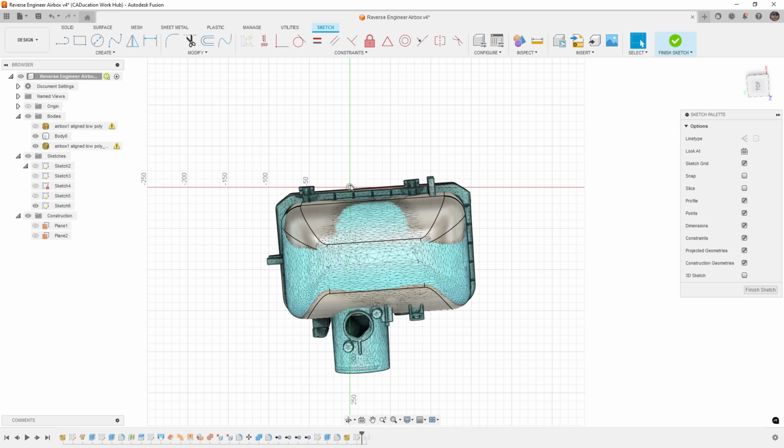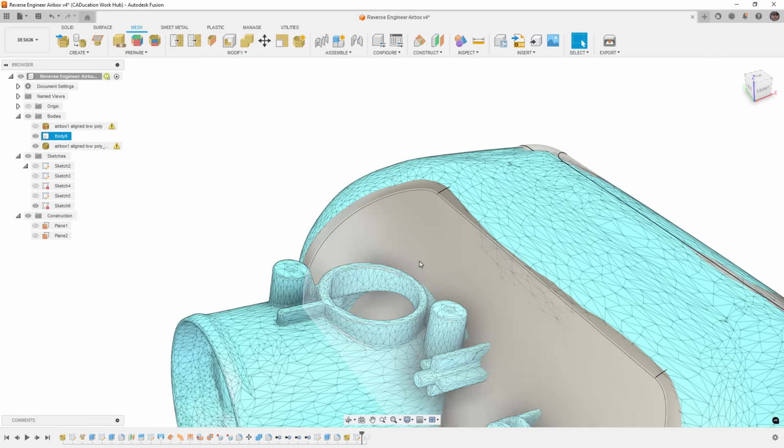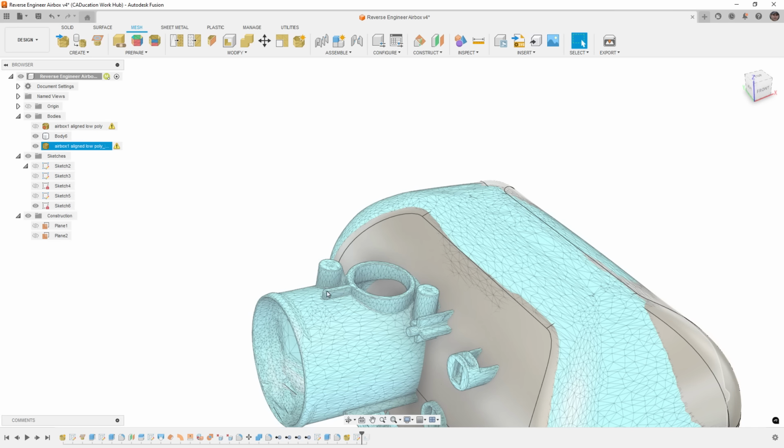The coordinate system is shifted. And when you first look at this, you might think the entire part shifted, but if you look at the view cube up in the top right, you'll see that the default or the normal origin is rotated, but our sketch origin is based on the orientation of the 3 points we selected. Because of that, that can be tricky, especially when you're trying to make something like this rib here that should be in line with this, which technically should be in the x-axis.